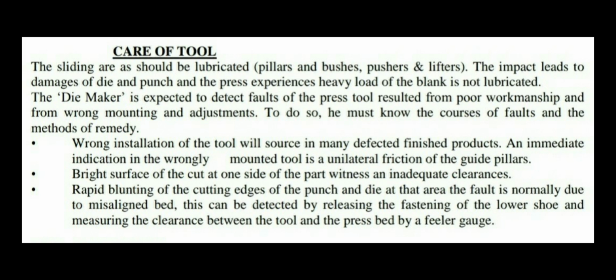So wrong installation of the tool will result in many defects, finishing problems. An immediate indication of the wrongly mounted tool is unilateral friction of guide pillars. So bright surface of the cut at one side of the part is witnessed as inadequate clearance.